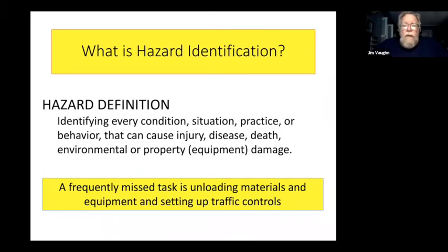That was the only injury on the whole 4 month site, working 10 hours a day, 7 days a week with 35 personnel on the site. And they didn't do a hazard analysis. The truck driver operating the all-terrain forklift did not talk to the apprentice about what his role is and how they were going to pick this stuff up, or what the hazards were, or what they were going to do. They did not do it.